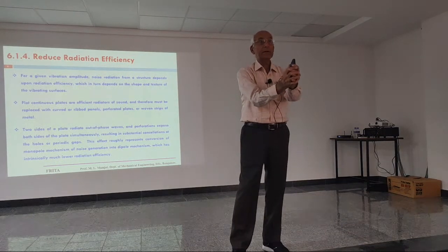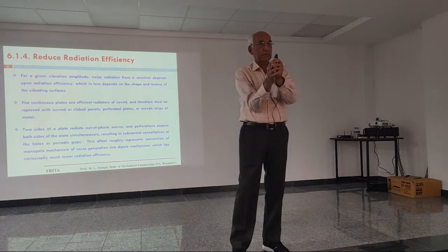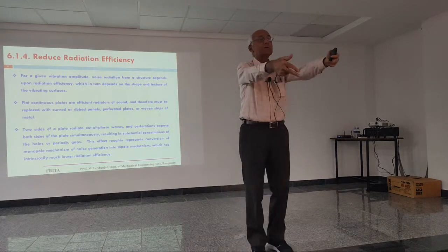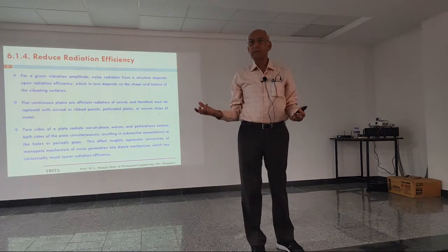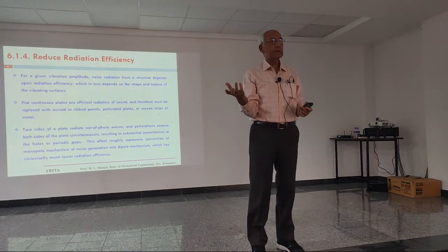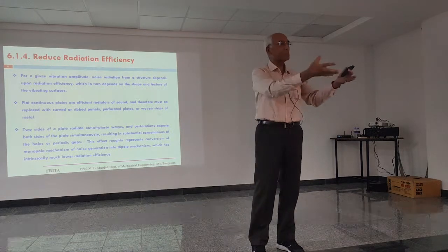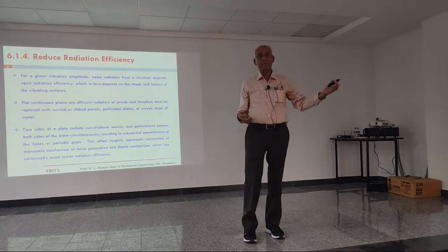Now, this coupling can be very, very risky, so people have to be protected from that just in case something happens. So you want to make a cover, and that cover doesn't have to be solid. Make it of a perforated plate, mesh. Mesh is good enough because all you want is mechanical protection. And then you will find there is no noise at all.